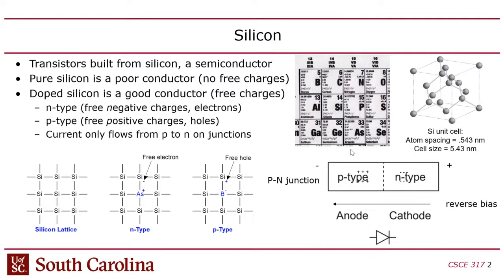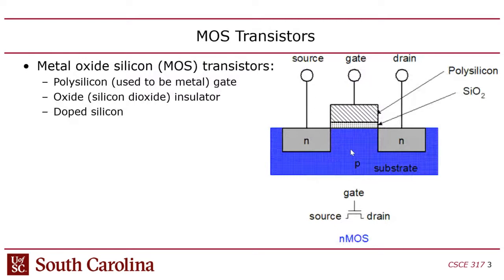So once you get down to 5 nanometers, you're only going to have enough room in there for one unit cell. And once you get less than half a nanometer, you're basically smaller than the distance between atoms. So you can't really go any smaller than 0.5. We're basically at 11 nanometers as compared to about 0.5, so we're about 22 atomic widths at this point. But you can imagine that you can't continue shrinking that indefinitely, because you're limited by the atomic width.